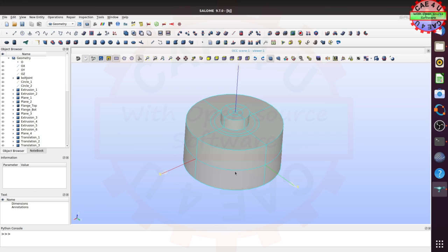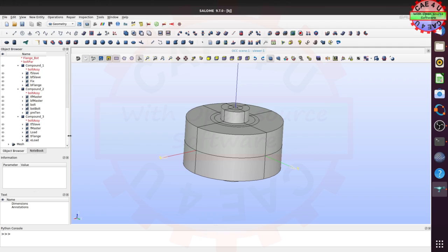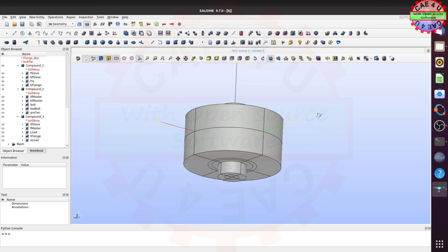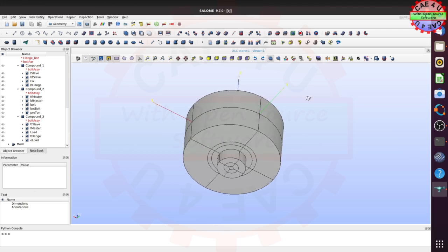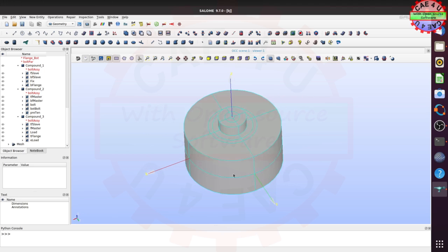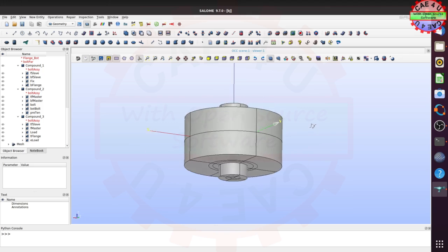While dealing with pretension, Calculix seems to have some limitation in terms of defining the contacts for bodies having pretension. For instance, it is better to keep a small gap between the contact surface of the bolt head and the surface where load or boundary conditions are defined. Calculix does not support defining internal surfaces, so a separate body has to be created for defining the pretension section.